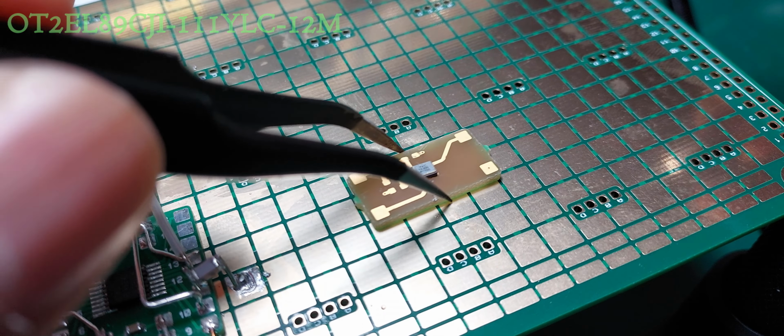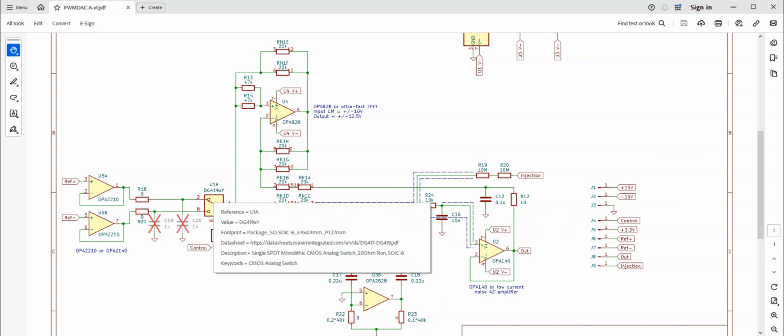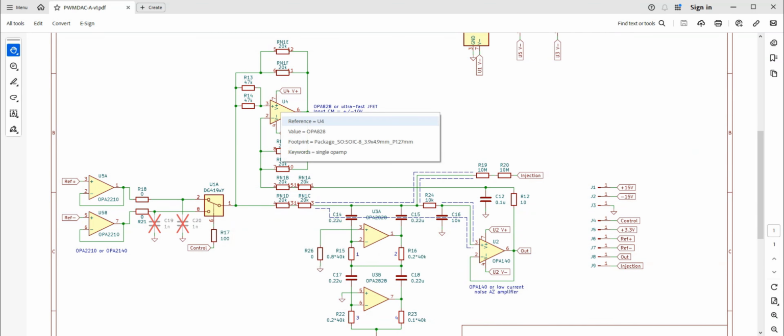If the resistor values are calculated correctly, no current flows into and out of the analog switch except during the op-amp's slew time. Connecting one end of the circuit to the DC output and the other to the analog switch lets the op-amp calculate the exact current that will flow into and out of the integrator resistor as the difference between either analog switch state, that is, the reference voltages, and the output. On the oscilloscope, it looks something like this.